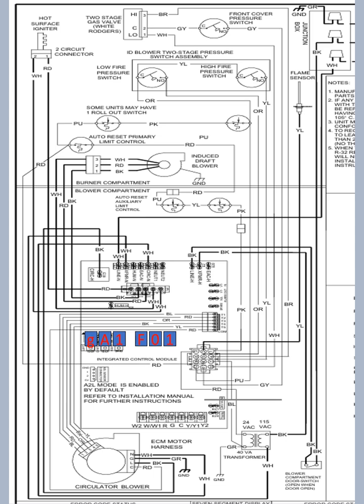You will also see that the board from now on will start alternating between GA1 and FO1, which is your first stage call for heat and your first stage call for the blower airflow or speed.